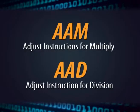The multiplication and division operations can be performed when the numbers are represented in packed BCD format. Assume the two numbers, whether 8 bits or 16 bits, are represented in packed BCD format. When these two numbers are multiplied or divided using the mul or div instruction, the adjust instruction for multiply and the adjust instruction for division transform the result back into BCD format.